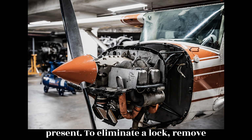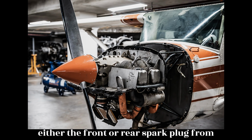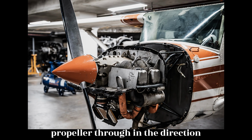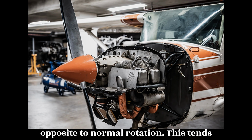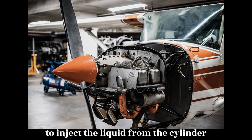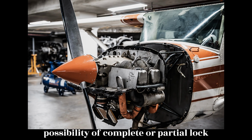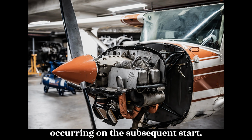To eliminate a lock, remove either the front or rear spark plug from the lower cylinders and pull the propeller through. Never attempt to clear the hydraulic lock by pulling the propeller through in the direction opposite to normal rotation. This tends to inject the liquid from the cylinder into the intake pipe. The liquid is drawn back into the cylinder with the possibility of complete or partial lock occurring on the subsequent start.